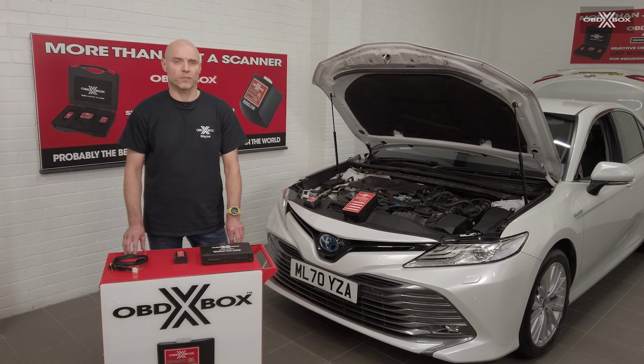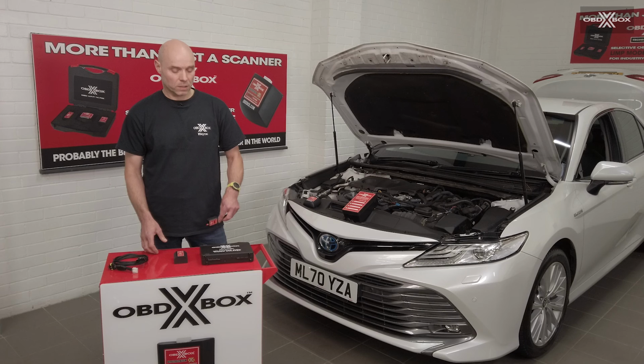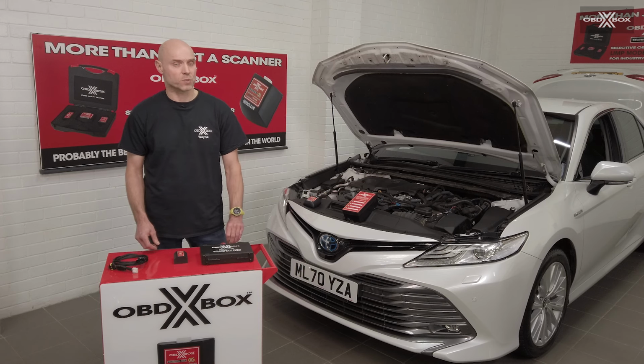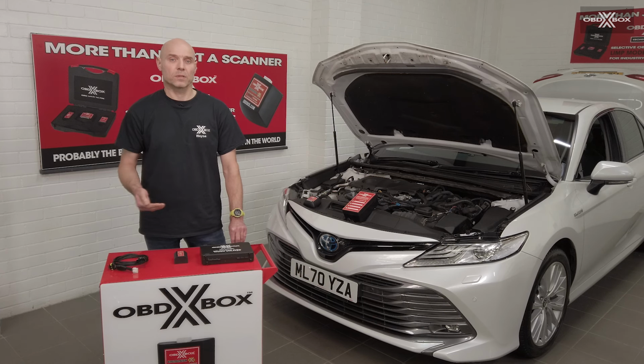Because of the time-consuming nature often encountered with intermittent faults, it's better to allow the customer to do their own test driving. They often enjoy being part of the process, and if you don't have time immediately to deal with the customer's fault, they don't feel like they're being fobbed off when you send them away with a fix assist unit connected to the vehicle. You can also connect a DTC alerter to the vehicle so that they're informed when a fault has appeared and been deleted. And it will help them get a mental picture of the situation, the conditions that were prevalent when the fault occurred. I'd like to introduce you to the DTC alert function.